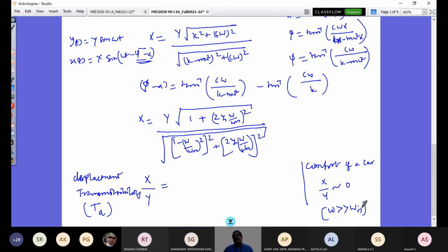That means the natural frequency of your system is there. Your vehicle vertical natural frequency, sprung mass, is there. So I would give you that value around 1 hertz for any vehicle design. So if you look at that, it would be around 1.05 like that. That is the frequency. And you see your road excitations are in higher frequencies, say 1000 hertz, 2000 hertz, road profile. It's a very smooth road, asphalt road. You would see absolutely there is no bounce in your vehicle.